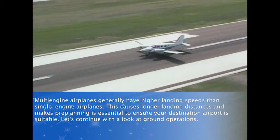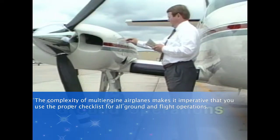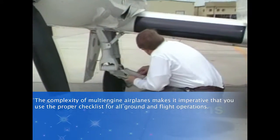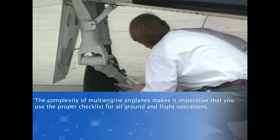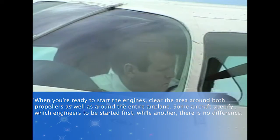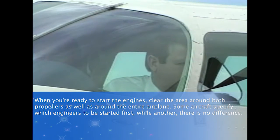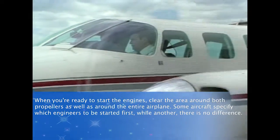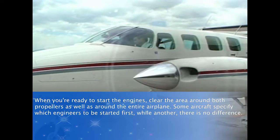Let's continue with a look at ground operations. The complexity of multi-engine airplanes makes it imperative that you use the proper checklist for all ground and flight operations. When you're ready to start the engines, clear the area around both propellers as well as around the entire airplane. Some aircraft specify which engine is to be started first, while in others there is no difference.